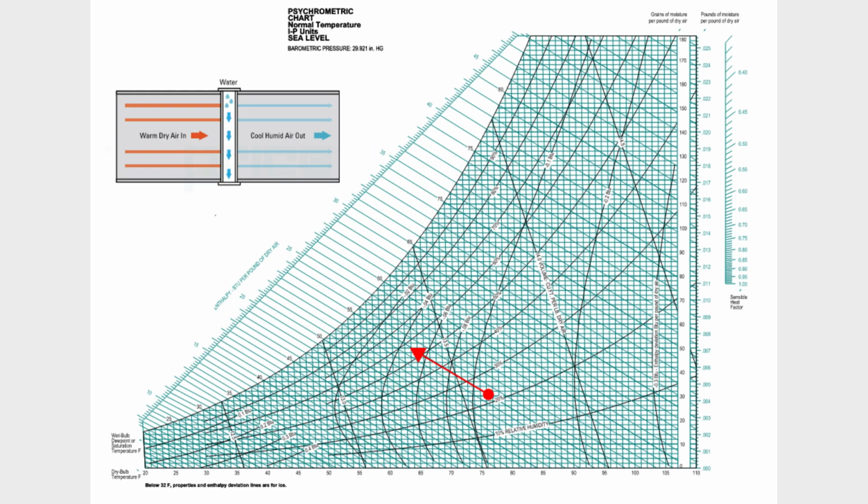Evaporative cooling, adiabatic process. Next is one of the most energy-efficient natural cooling methods, evaporative cooling, also known as an adiabatic process. Here, water evaporates into the air, which increases humidity while lowering temperature. No external heat is added or removed. The total heat, or enthalpy, stays constant.